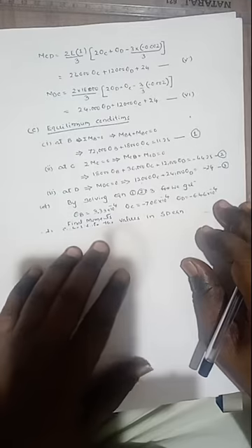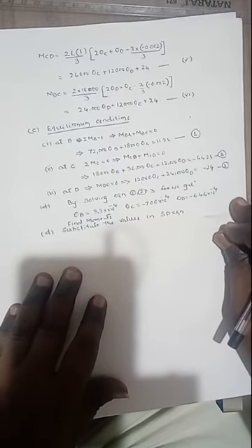Now, after getting the values of the slopes at B, C and D, they are the unknowns. In the slope deflection equation, either the slopes are unknowns or the deflections are unknown. Here theta B, theta C are the unknowns. By substituting the values of theta B, theta C and theta D to get the final moments, hence, by substituting the values in the above slope deflection equations, that is 1 to 6,